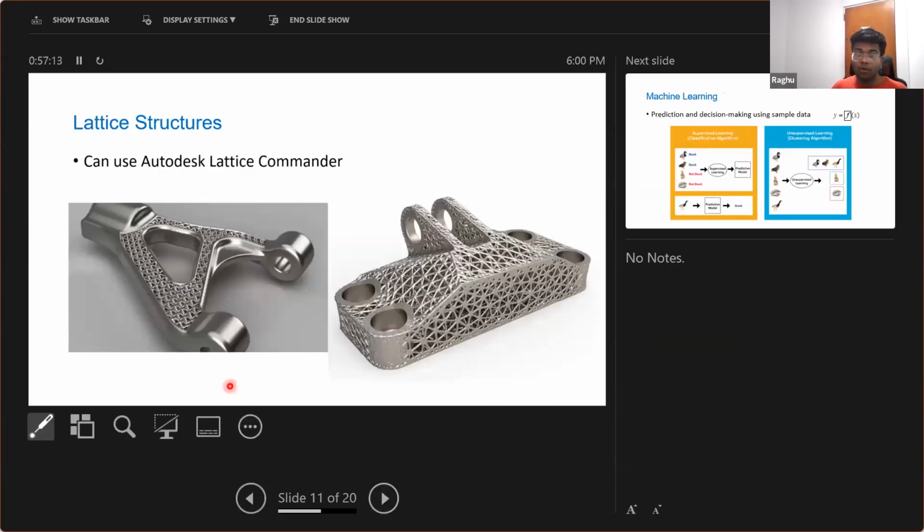So, okay, this is one more interesting thing which has been happening for the last 3-4 years. It is something called lattice structures to make it much more lightweight, and this is completely because of additive manufacturing. I showed you this bracket before, right? So this bracket, instead of having the bracket itself, they fill it with something called lattice. These small minute structures which are repeated on and on. These things can only be made by additive manufacturing and not any conventional techniques. Since as you see this is very porous, this is definitely going to be much lighter in weight. So we optimize this lattice shape such that the structural integrity of the overall structure is still maintained, but it is very light in weight.